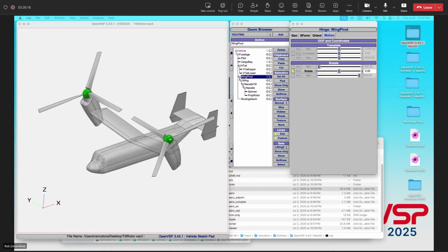You can, through the API, access the XYZ global coordinates of all the routing points. So there isn't an export like a CSV or another manual export of that at this time. But if you need that information, you can write a quick AngelScript or write a Python script and update your model, and then you can dump out the XYZ coordinates of all those routing points, and then you can do your own calculations from there.